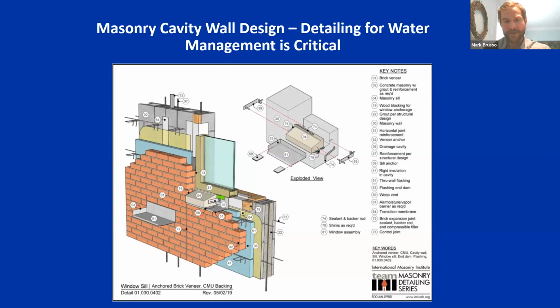This is another really great slide showing some of the best things to incorporate into sills and areas where water penetration typically is an issue, at windows, at through walls, wherever there's a change in plane or a seal detail needs to be located. These IMI documents are exceptional at showing some really good things to do and consider in terms of managing water with your detailing.